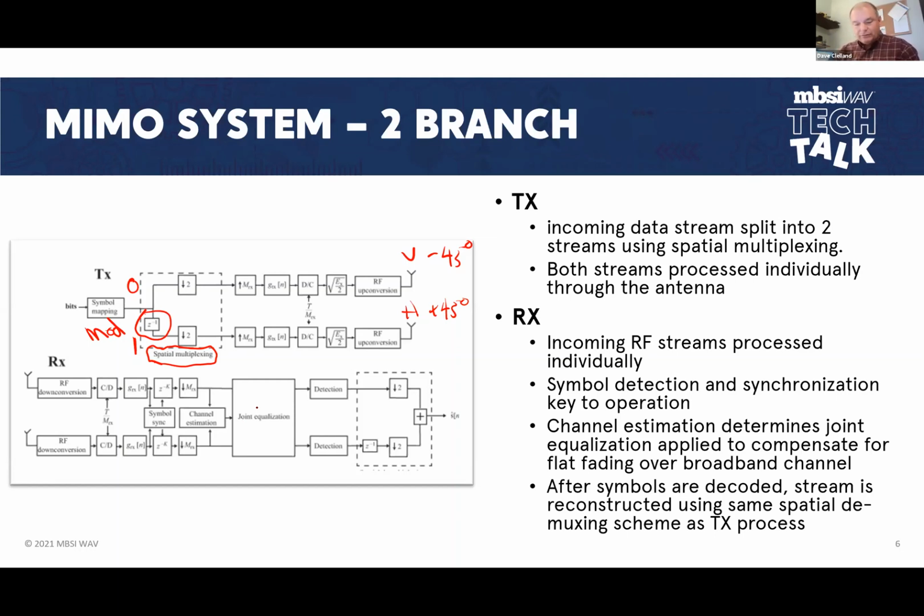Incoming receive streams. Of course, now we've got the same here. Let's assume that we're on dual slant antennas, so this one is going to be minus 45 degrees, and this one is going to be plus 45 degrees. Let me write that so you know it's degrees. All right. So there's going to be some difference between the 2 streams here, in this uncorrelated state, rather, we have whatever the discrimination is between the 2 polarizations as differences in the stream.